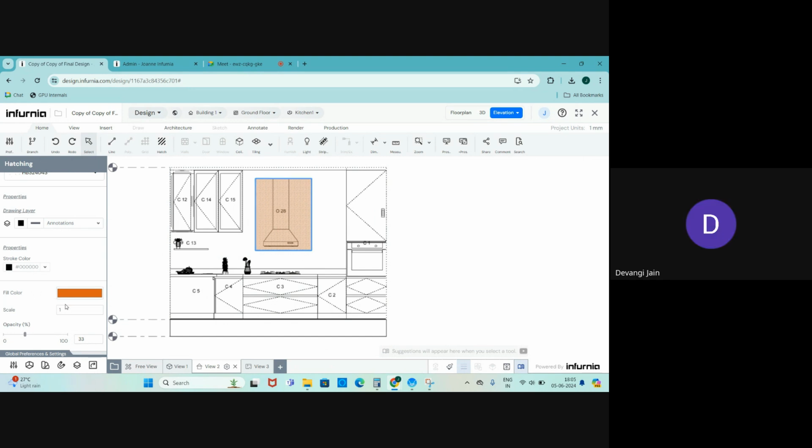The idea is, for example, if you have a kitchen with four elevations, and with each elevation you want to highlight that elevation only, we would have to make separate views for that, right? Yes, you will have to do that, but you can make these denotations in your elevation views and then simply move them to your presentation. And in your presentation, if you want, you can hide or unhide this.